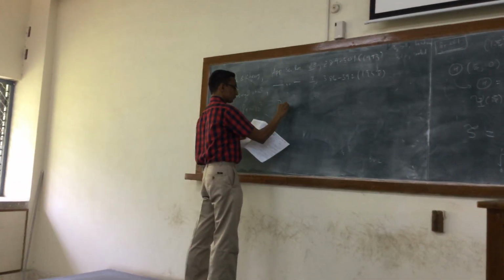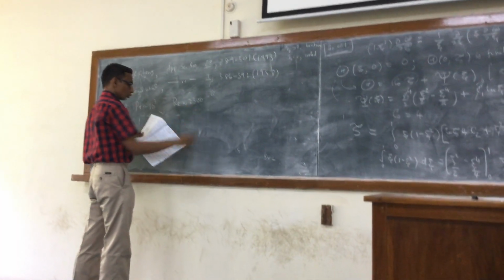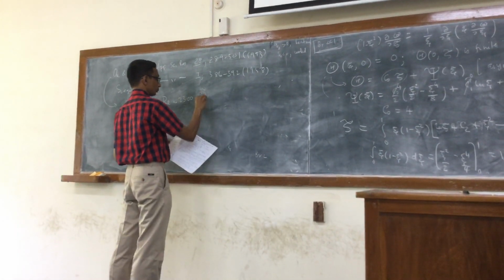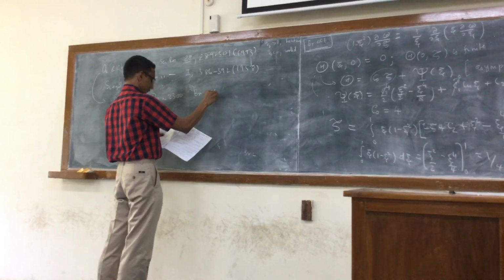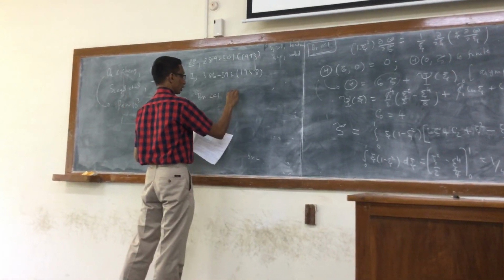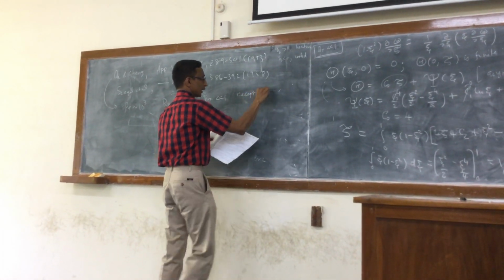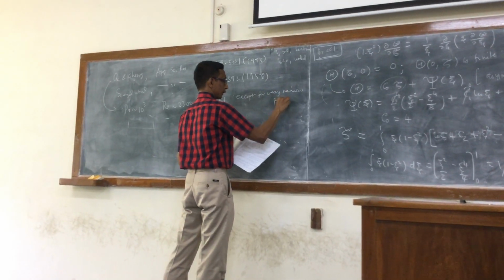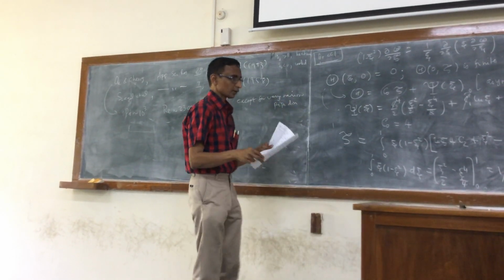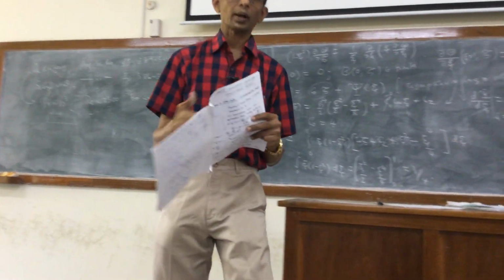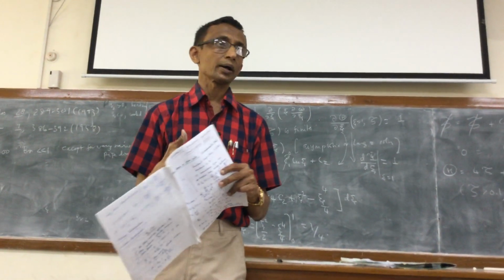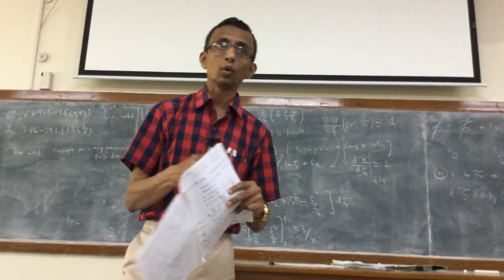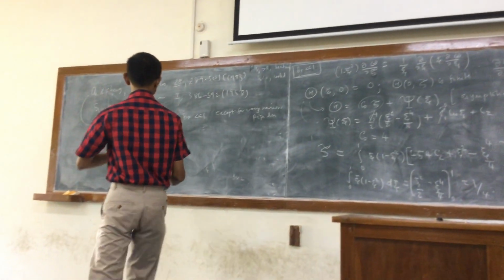So what they are saying is the Reynolds number 2300 corresponds to laminar flow, and they find that the Brinkman number is much less than 1, except for very narrow pipe diameter. We saw that the Brinkman number has a 1 over R, capital R, so R in the denominator, so it will increase at very low values of the pipe diameter.